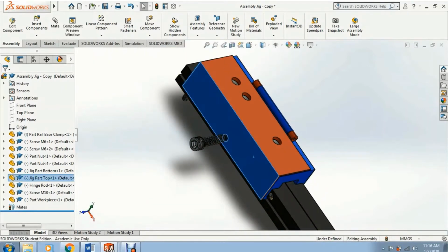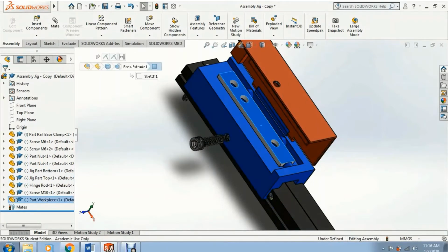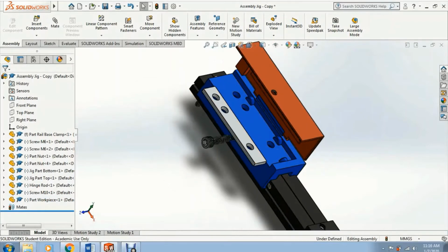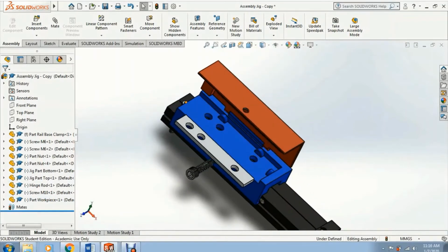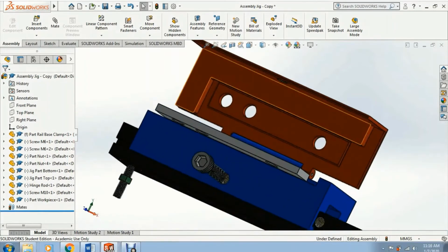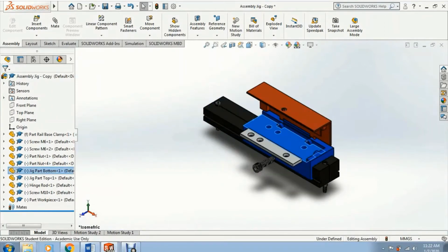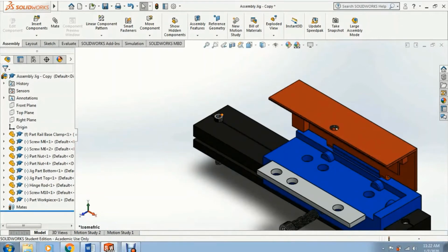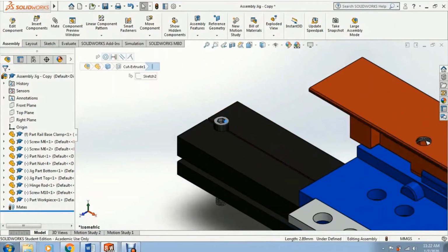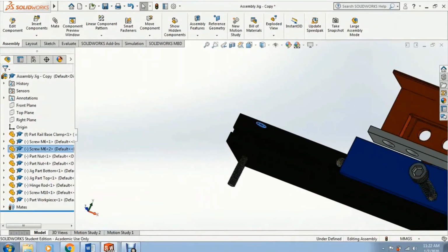And then this is the top cover, which also acts as the clamp for the workpiece. And then this is the workpiece design. And then so we can see here, this is the pin locator to position the workpiece. And then at the top cover we have the clamp for the workpiece. Okay, so we'll drag it here. So after finishing the first one, of course the screw must be open, so we can tighten it with a nut.